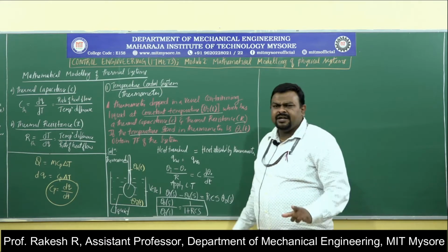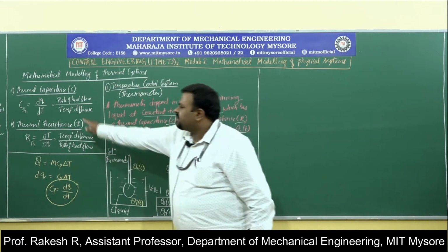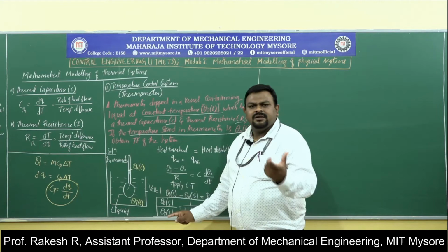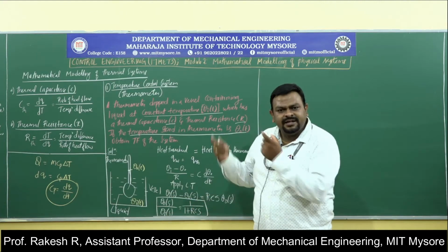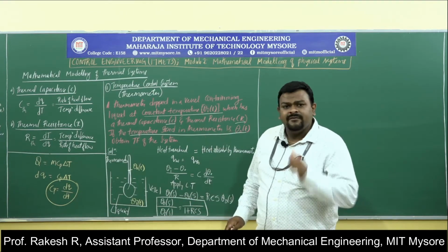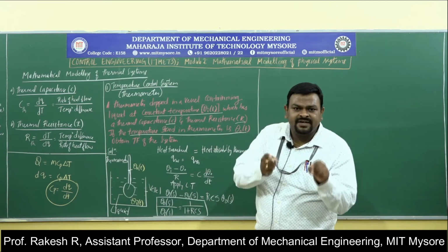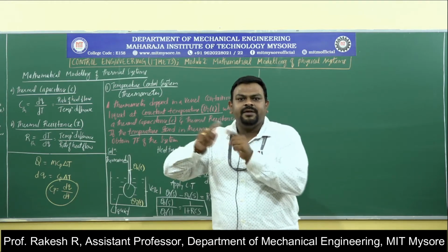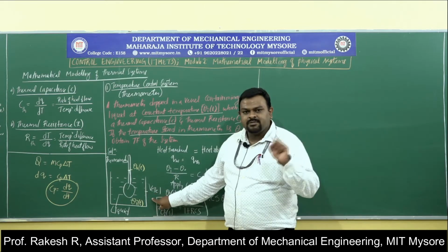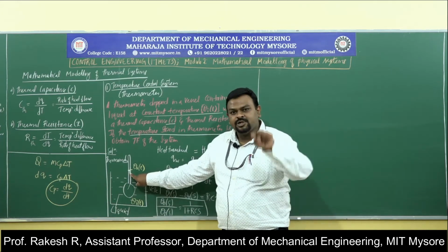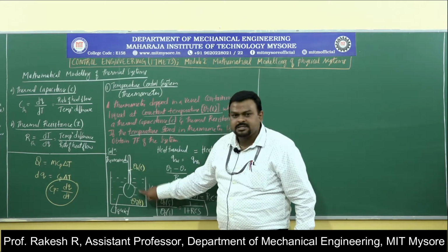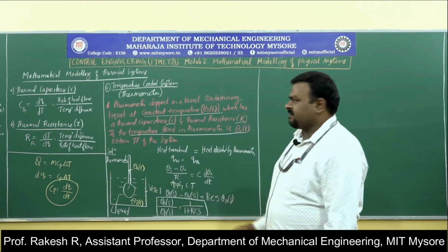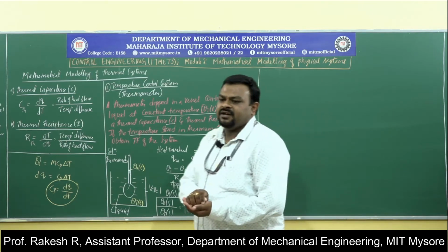What we have basically done is correlate the equation of capacitance as well as resistance. Capacitance is where it is storing the heat, in the thermometer. Resistance is where it is giving resistance, in the vessel between the water inside the vessel and the thermometer. So heat is transferring from water to thermometer and heat is storing in the thermometer. Here there is a resistance, here there is a capacitance. Equate those two things, you will get the final thing. So this is the temperature control system.